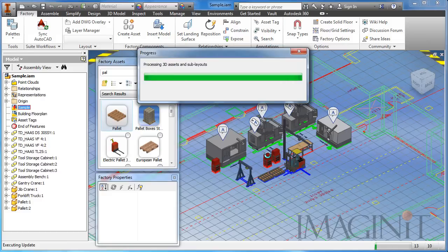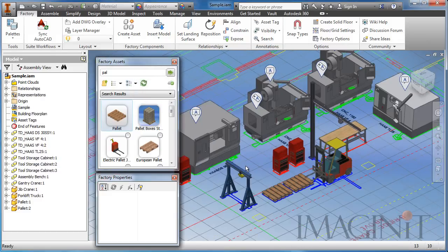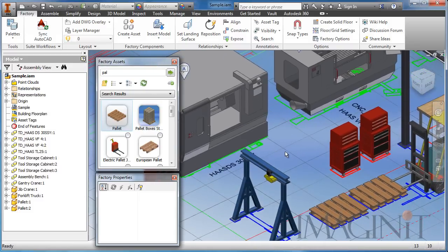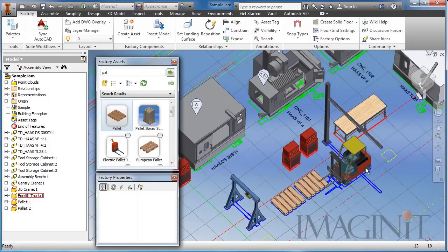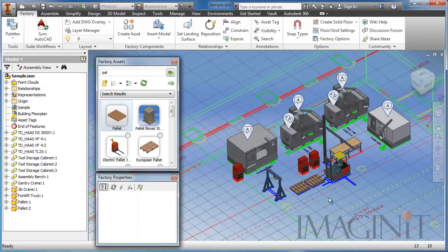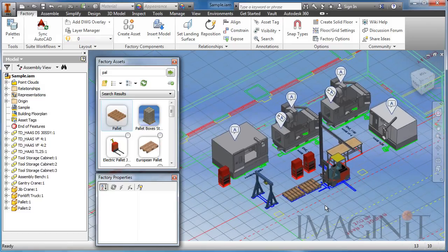And it makes it so nice to just be able to look at the text on the floor and determine what that particular asset is. Very, very nice and very efficient way for us to handle something like an asset tag or a descriptor. You don't have to see the asset tags and the descriptors. There is a visibility option, so you can come up and turn those things off if you need them off or on.